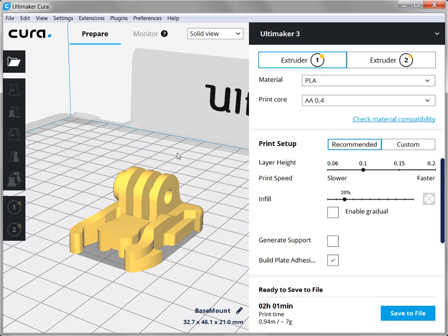If a part such as this one is intended to be structural and withstand stress, the printed layer should be perpendicular to the direction of applied stress. Since the direction of the layers on an FDM printed part are the weakest, the strongest part will be created if the applied load is perpendicular.